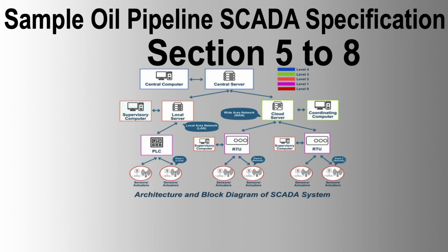8.2.2 System Logging. All operator actions and PAS system calls via the SCADA Operator Console shall be logged on the SCADA System Event Printer. The printer shall log all events arising from the PAS system. Types of reports supported: post-mortem reports defining values and status of key variables in the preceding period, daily report summary of system performance, configuration report. Additional printer can be connected to handle PAS reports due to activity by the system engineer, redirecting all output from the PAS, logs, reports, event.